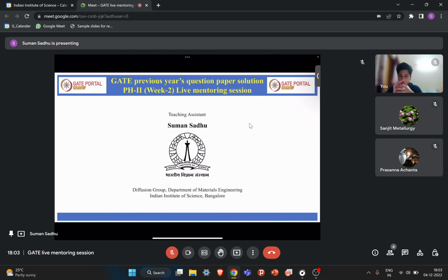And then there are different extractive methods, like molten bath aluminum extraction. So then the aluminum is extracted from this ore. So this technique is called selective leaching. Here chemical reactivity plays an important role. The chemical reactivity of Al2O3 and SiO2 or silicate is different. So using this principle, the Al2O3 gets separated from SiO2 and other gangue particles. Understood?